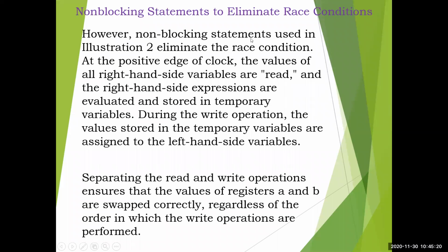However, non-blocking statements used in illustration 2 eliminate the race condition. At the positive edge of the clock, the values of all the right-hand side variables are read, and right-hand side expressions are evaluated and stored in temporary variables. When it comes to the write operation, that means assignment, after a delay, the values stored in the temporary variables are assigned to the left-hand side variables.